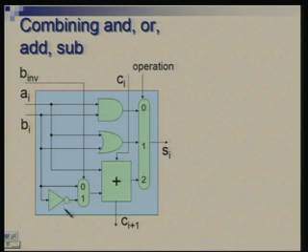So, effectively the circuit is always there for performing all the operations, right. You give some Ai and Bi, and the circuit would do the AND operation as well as the OR operation, and one of the 2 among addition and subtraction, but you are picking up only one of the results, right.